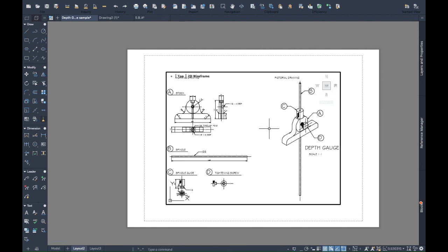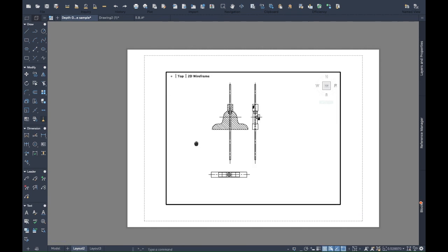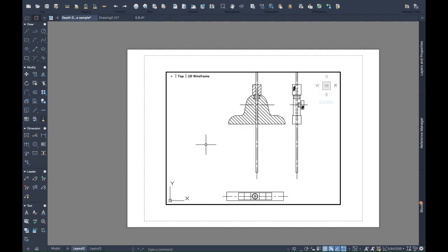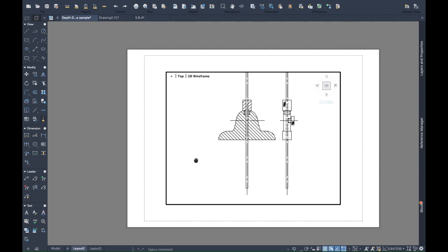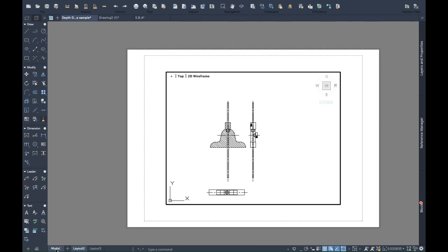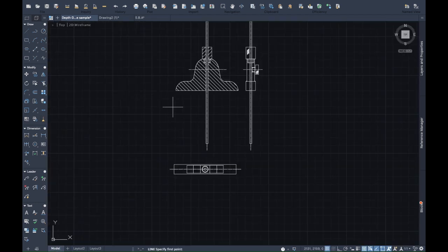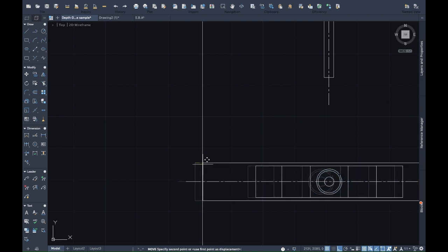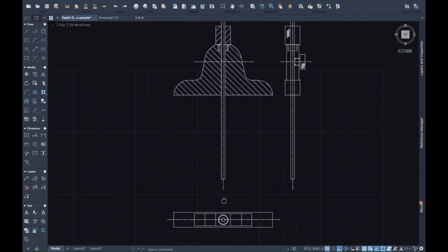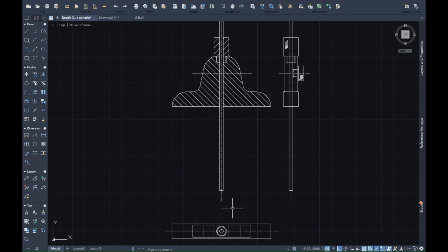Double click into paper space and slide over. Alright, so it looks like it can hold. So it can hold, so we won't do anything to it. We'll just leave everything. So what I'm going to do now, I want to get a line. Let me turn on ortho. I want to get a line there, so I can move this now. I can move this and make it line up with there. So delete this now. So I know now that this is directly underneath that.